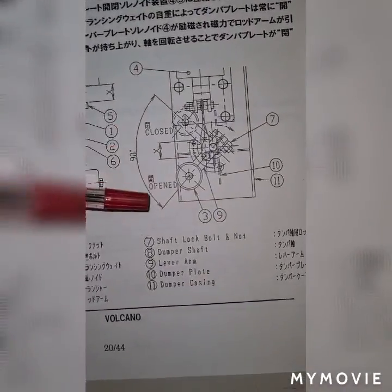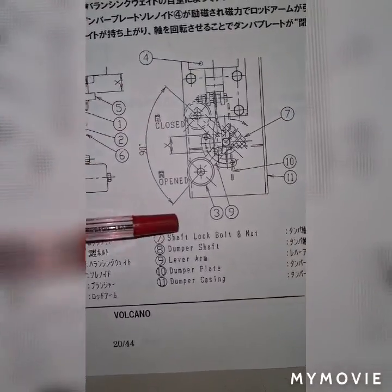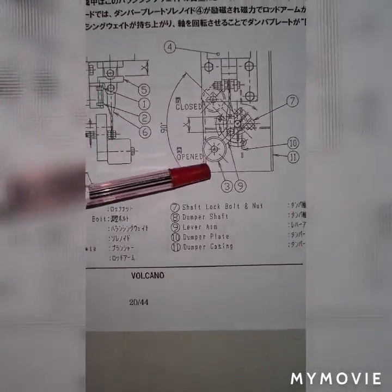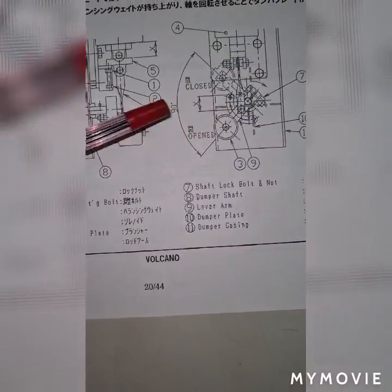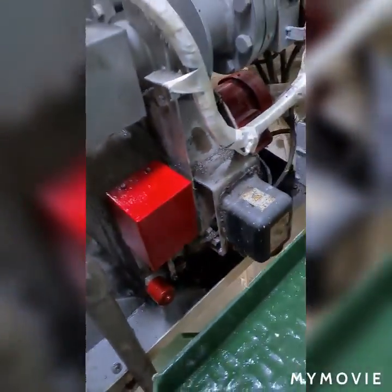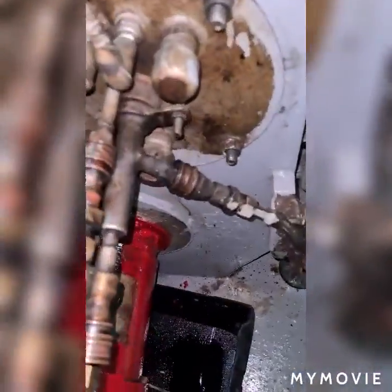As you can see here, once the counterweight is pulled, the air damper is closed by 90 degrees. When this is re-energized, the counterweight will fall down and the air damper will be open. While the air damper is open, the forced draft fan runs continuously while the boiler is operating, and while the boiler is stopped, this forced draft fan will continue running to perform a purging process.